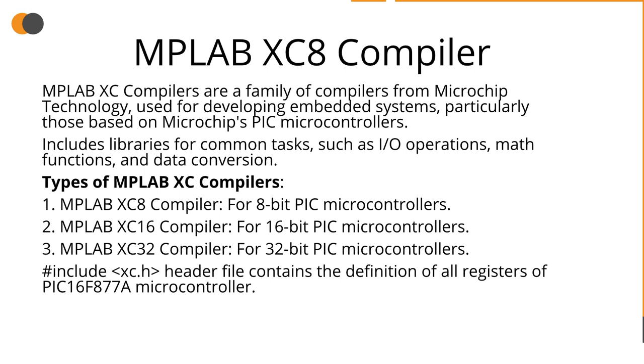The types of XC compilers are for 8-bit PIC microcontrollers, 16-bit PIC microcontrollers, and 32-bit microcontrollers. We use the header file, include xc.h, which contains the definition of all registers of the PIC16F877A microcontroller.